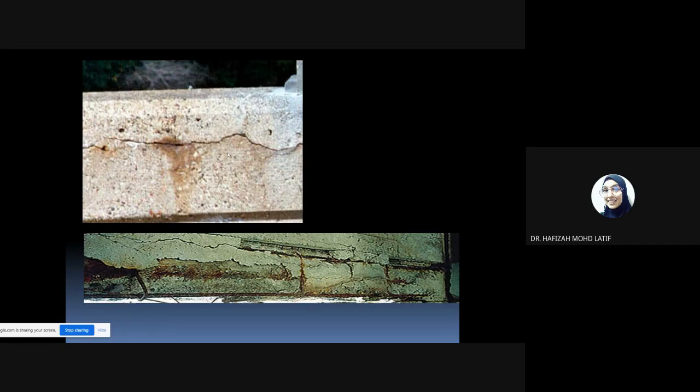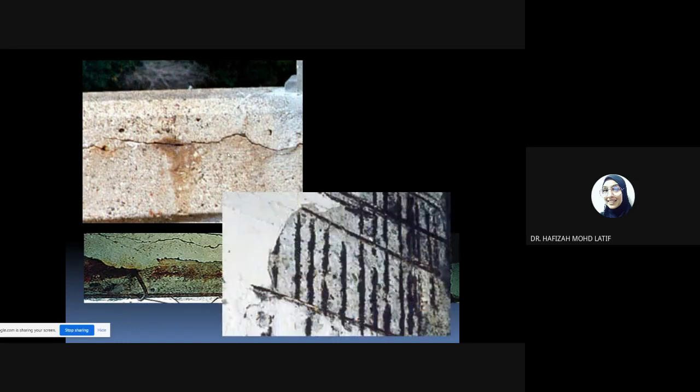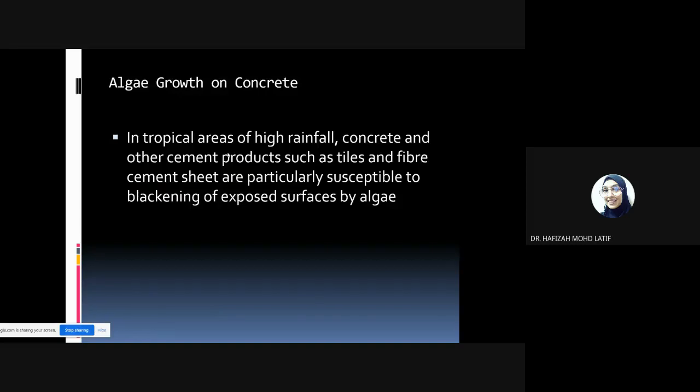You've learned that, right? But some sites don't use it, they just take small gravel stones and put them underneath. Cheaper, right, they don't want to buy those. They want to save the money, so they take big aggregates, and they will just tie it on the bottom of the rebar. Then you can have a nice concrete cover over the reinforcement bar.